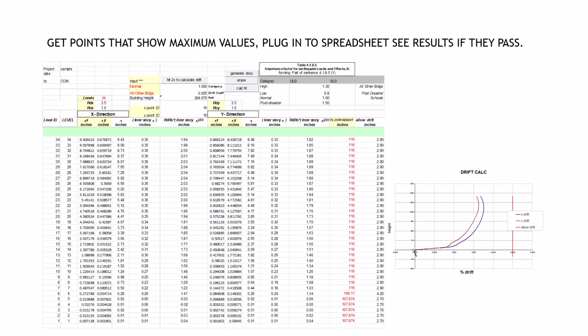Finally, analysis results are reviewed, including story drifts, base shear, and internal forces in the core walls. Special attention is given to coupling beam forces and overturning moments, since these control reinforcement design in coupled wall systems.